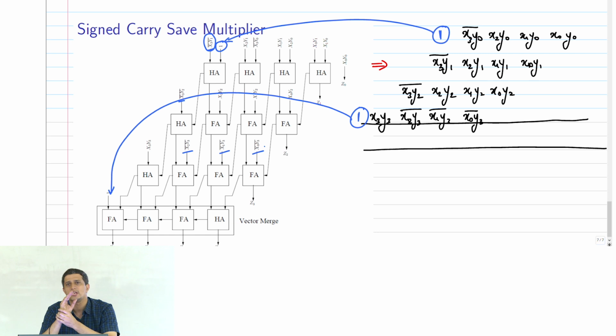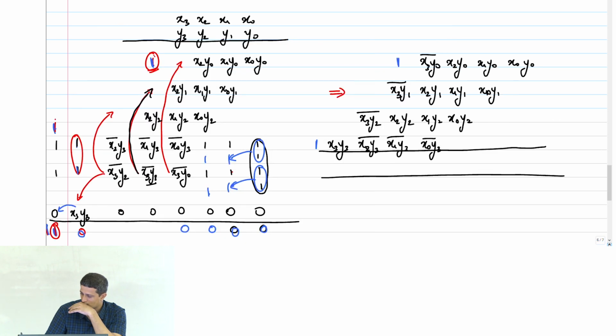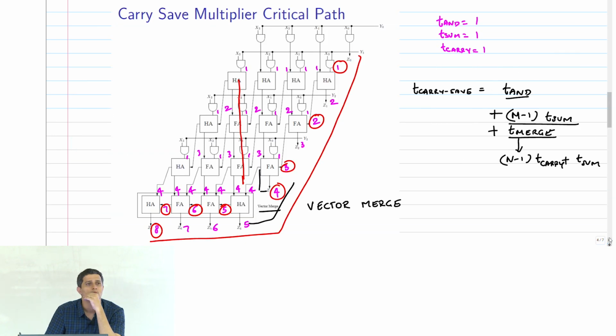Final thing I'm going to leave as an optimization for you in the project. All through we have done AND gates. But of course, since this is in the critical path, it's better I do NAND gates. If I make everything NAND, then I need to change this. It has to become a half adder prime, in the sense where it takes complements and gives out complements. So when you design your multiplier, please make sure you optimize for this NAND gate as opposed to trying to use an AND gate.